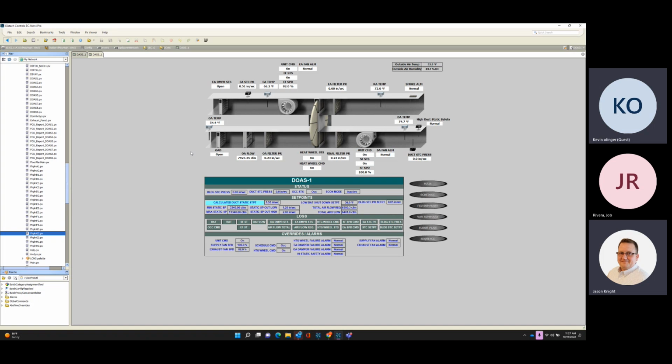And if they don't hear it, there's a problem, right? So I think the initial shock, we're hopefully on the back end of that. We still get some complaints here and there about like, I don't hear it running, but it's not that it's not running. It's just in ventilation mode because the space is satisfied, the CO2 level is good, and it backed the fan way down.